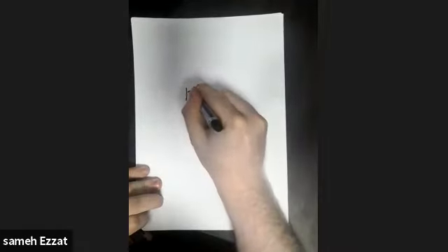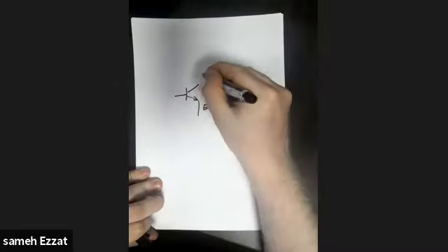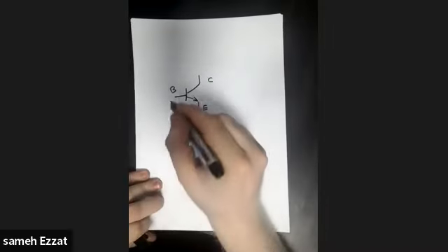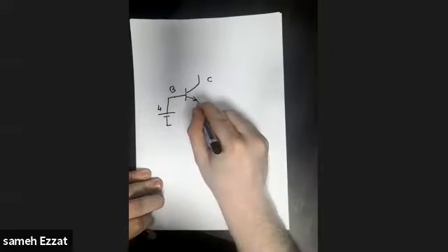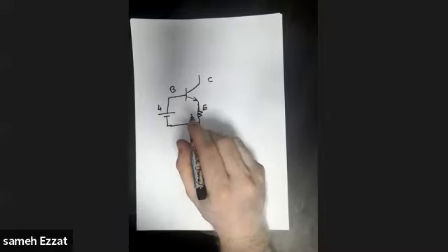In this part, we are going to solve 3 examples mentioned in the lecture related to the DC analysis of the BJT circuits. Let's now start with example number 1, where we have our BJT transistor. It's an NPN BJT transistor because, as you can see, the current is going out of the emitter. Here is the collector, and here is the base. Here we have a battery connected with 4 volts. Here we have a resistance connected to ground. The resistance here is 3.3 kilo ohm.